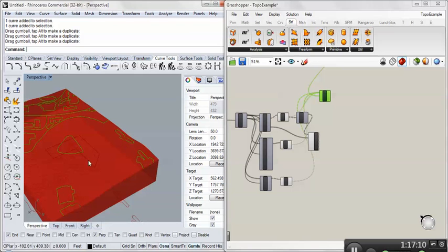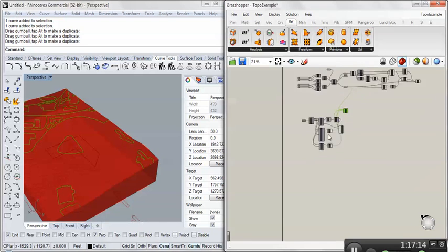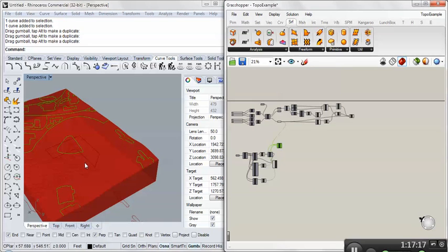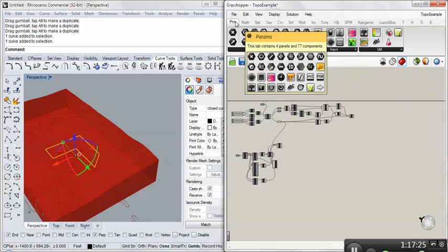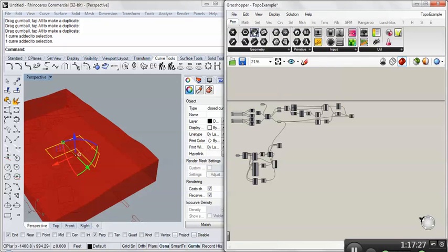All right, so now we're going to do a volume out of that in the same way that we did the other one. But this time I don't have this in Grasshopper. This is just in Rhino. So to import that geometry, we didn't have to do this yet today. This is under params. This is a curve, so I'm going to do that.